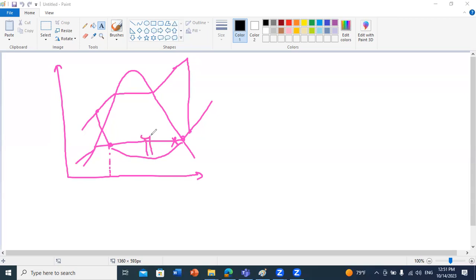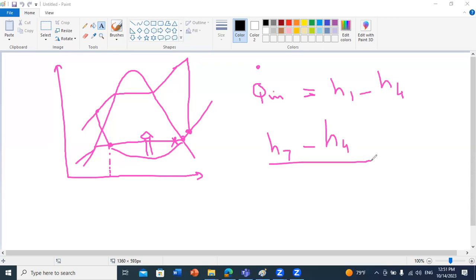Q extracted from the refrigerator. In order to increase Q dot N, which is equal to the difference H1 minus H4, it's desired as much as possible to start higher. Of course, we should pay attention that what counts at the end is the ratio. The COP is Q dot N, which is H1 minus H4, over H2 minus H1.